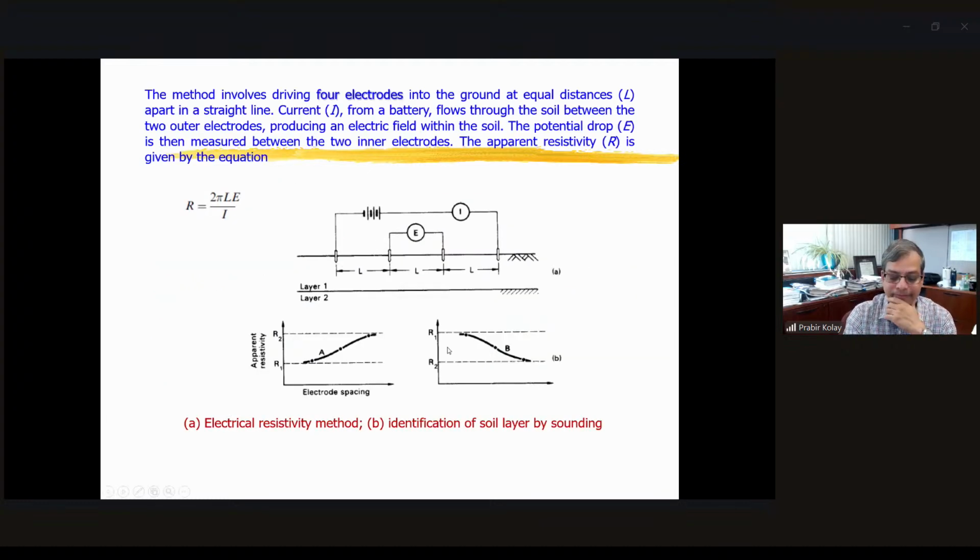All right. So yeah, I know that I go quickly, so there are so many. Basically, the borehole is most important. You collect the soil sample using different sampling techniques, and then put it in a bore log with the depth, what type of sample it is, mostly the N value, and the location of the water table. That's the main thing. As I mentioned, this is like a blood test report.